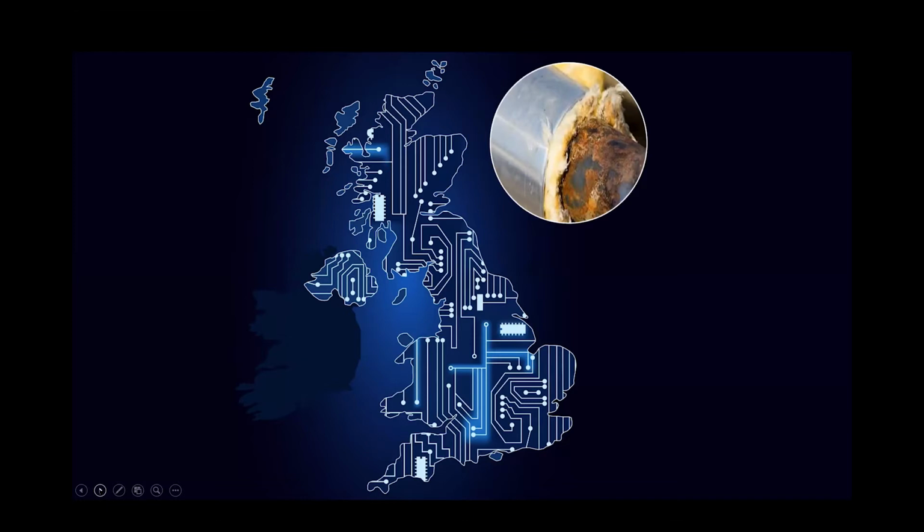It's estimated that CUI poses a significant operational and safety challenge and is one of our highest integrity threats. Many of our assets in the UK continental shelf are operating well beyond their design life, and we are now seeing more and more failures attributed to CUI. As a result, it is estimated 60% of all piping failures are attributed to this failure mode.